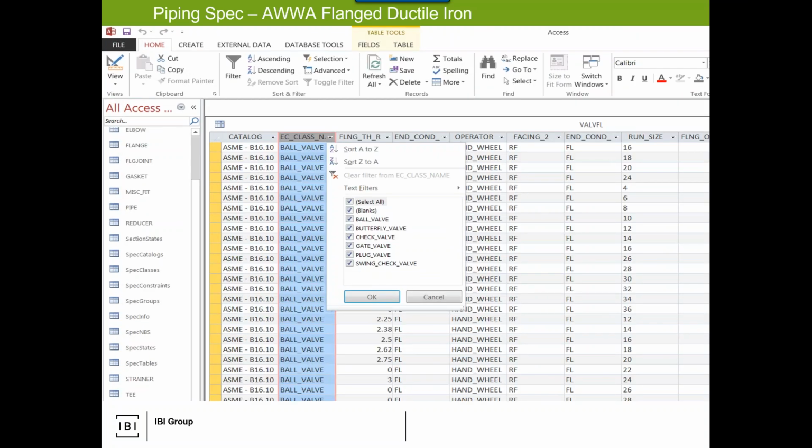So here's an image just showing the valves. So these are all of the valves that are available. So the sizes for the valves. If a client says, so I don't know if you're familiar with any of these, but a ball valve is probably the most typical. If you have a house and you turn the crank to turn off your water, the ball valves are the easy ones to turn, whereas a gate valve is your typical exterior tap. It turns and it closes a gate, shut the water type thing.